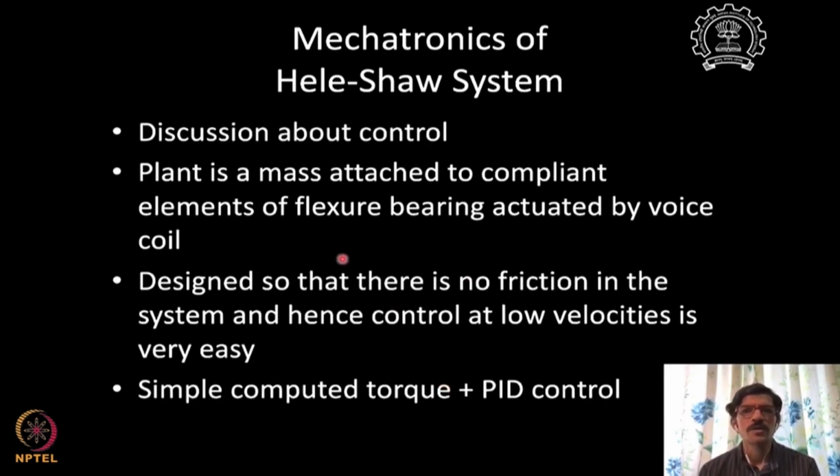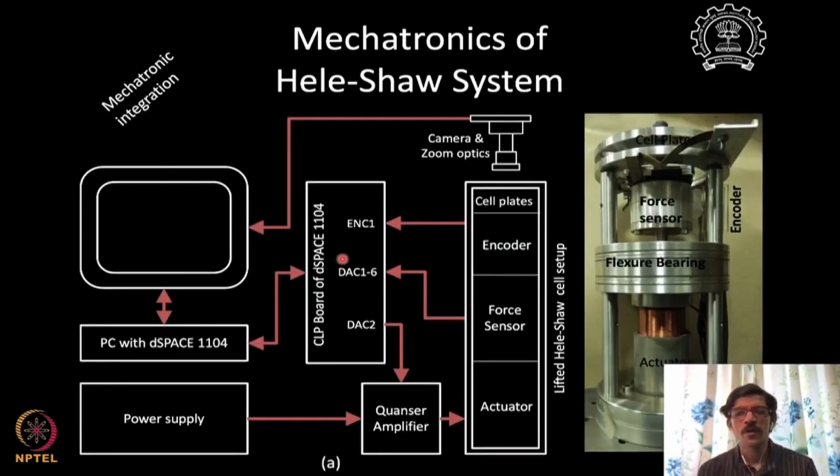Now let's discuss a little bit about control. After seeing this system here, what kind of thoughts can you gather for really exercising control over this system? We want to basically move this upper plate in a very controlled fashion, to pull it down and execute our process. We want to maintain some fixed velocity as we pull it down. If this plate is pulled down, we want to maintain a fixed velocity, say 5 micron per second or 10 micron per second.